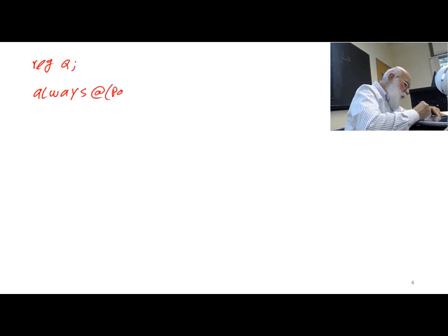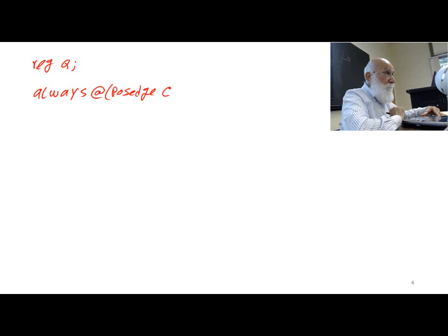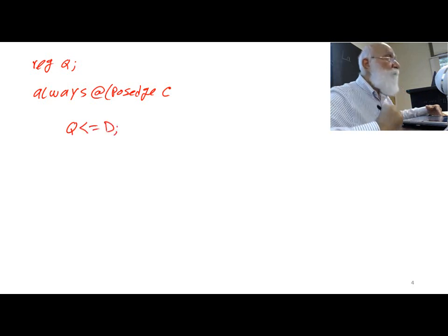You still have posedge of clock. There's no if for now. Then you say posedge of clock, like we have done before, Q gets D.